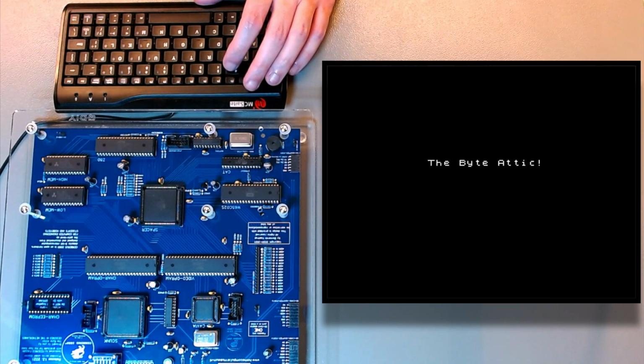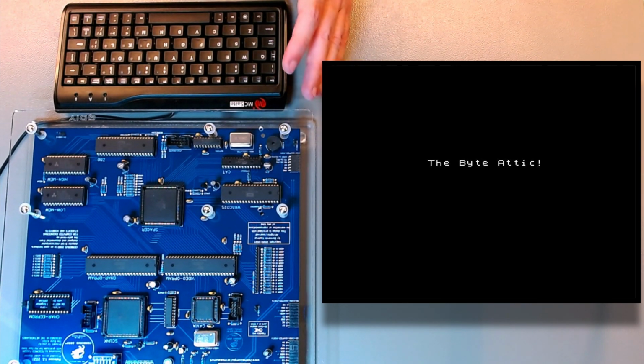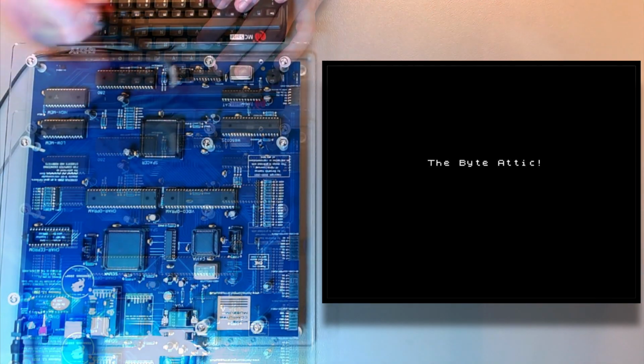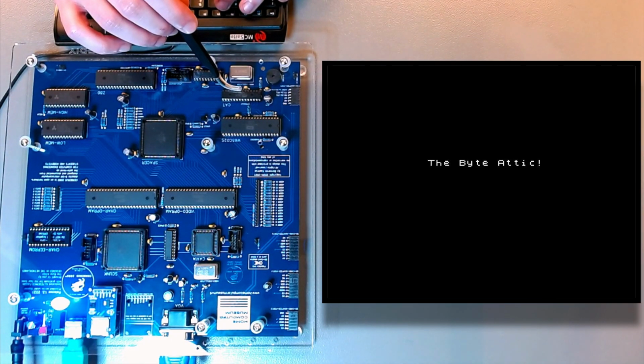communication between CAT, the I/O processor, which reads the keyboard, and the currently active CPU, in this case the 6502. They communicate with one another via memory-mapped I/O. When a key is pressed, that's the keyboard input, CAT will be interrupted.